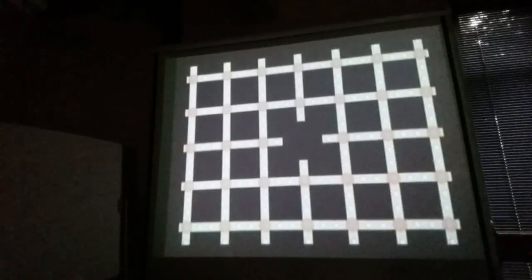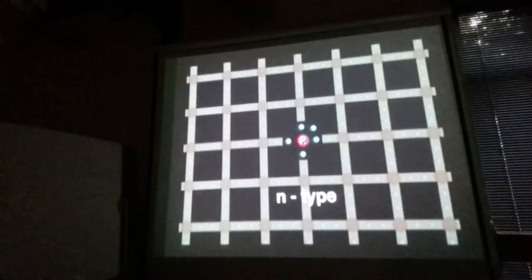One can make N-type silicon by adding impurities, such as phosphorus with 5 valence electrons, one more than silicon. When in the crystal, 4 of its valence electrons form complete bonds with neighboring silicon atoms. This leaves 1 extra valence electron that will orbit the phosphorus in a Bohr-like orbit at very low temperatures, but will diffuse through the crystal at ordinary temperatures.